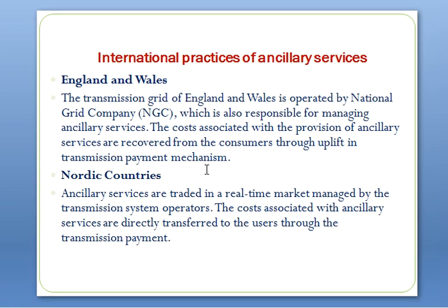For the frequency control, the system operator is required to keep the frequency between 49.5 and 50.5 Hz. In the case of a contingency, the frequency is allowed to drop under 49.5 Hz, but not for more than 1 minute. The supply of primary frequency regulation is mandatory for all the generation with an installed capacity of over 50 megawatts, which must provide the service continuously. Generators are set up for a drop of 3 to 5%.